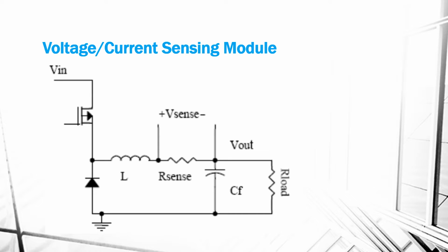An alternative method to using a voltage divider can be achieved through resistive current sensing, which is done by inserting a very low ohm resistor into the circuit. We can then measure the voltage across the resistor and therefore calculate the current using Ohm's law. The addition of the resistors does cause a small power loss, but it is less than the loss a voltage divider would generate.